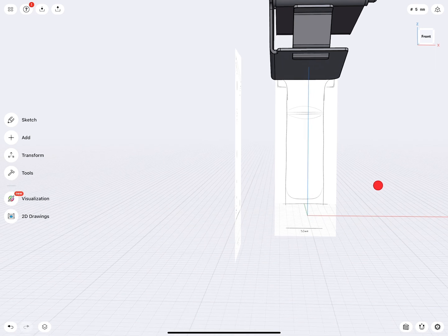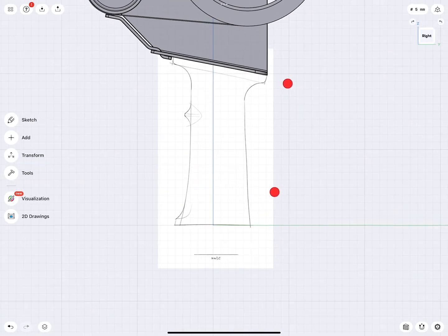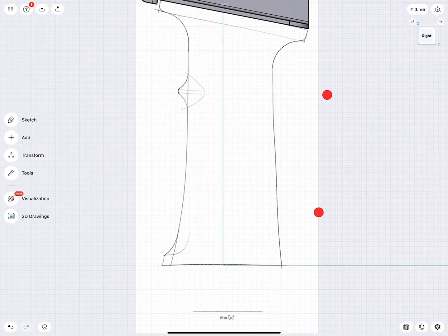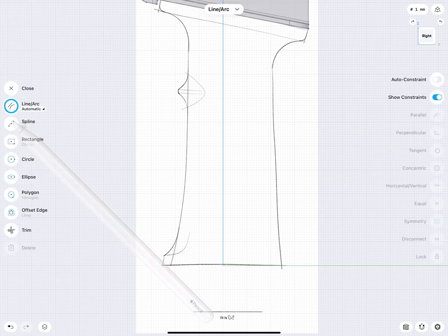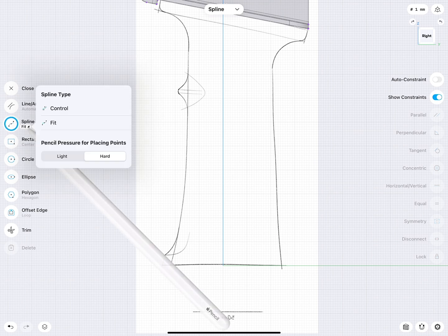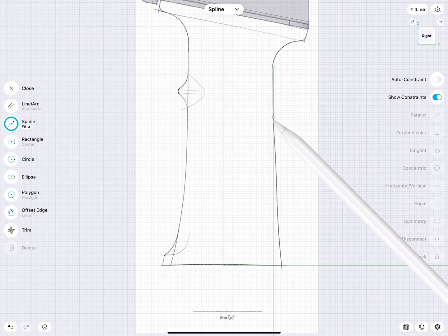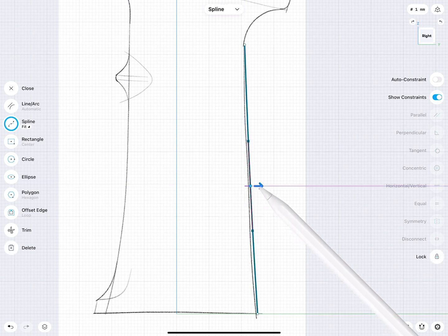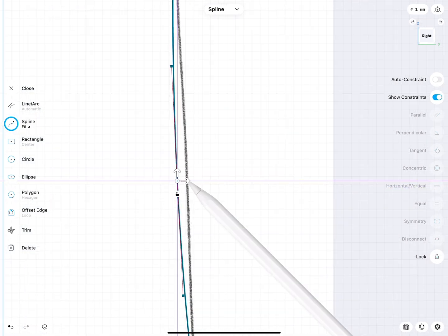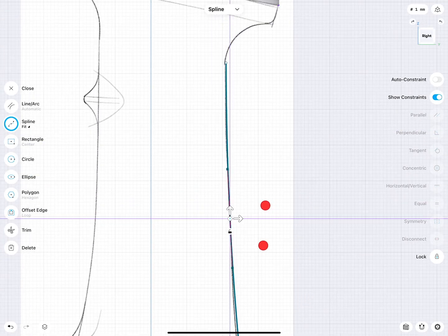Okay, so how do I now start? This is very linear. The sides are vertical, which means I can start from this view and do an extrusion. So the first step now would be to create a sketch. I can go to sketch. I can use the fit point spline, or if you would like, you can also work with the control point spline. And now I can explore where and how I have to put my 3 points to make a nice arced or curved curve.